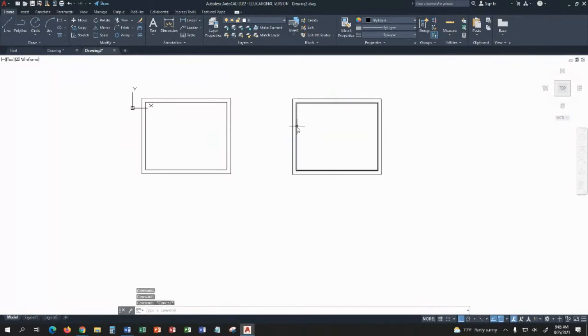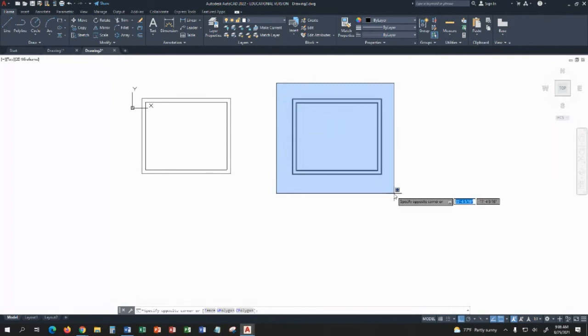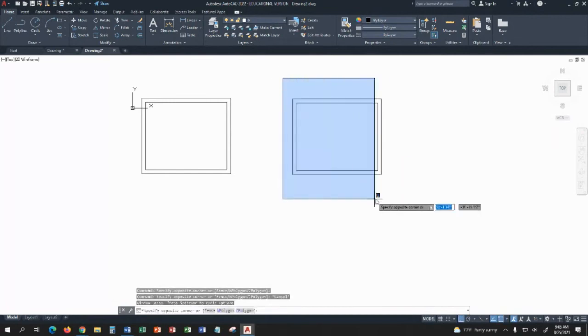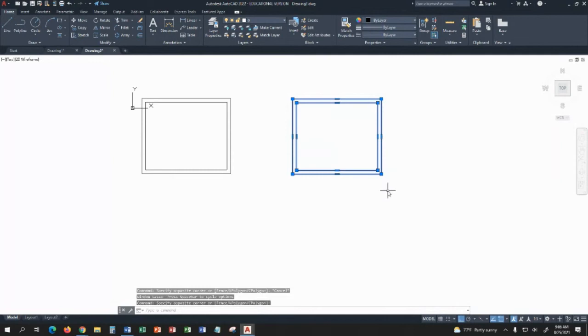So this is 2 individual lines, 2 polylines. What I want to do to make them 4 lines is explode them. And the way you do that is you put your mouse here and you create crosshairs over that. If I put my mouse here and I hold down, I'm going to create some funny, goofy thing. So click, drag, click. Then I've selected that whole area, and I can type in explode, and I've got that exploded.